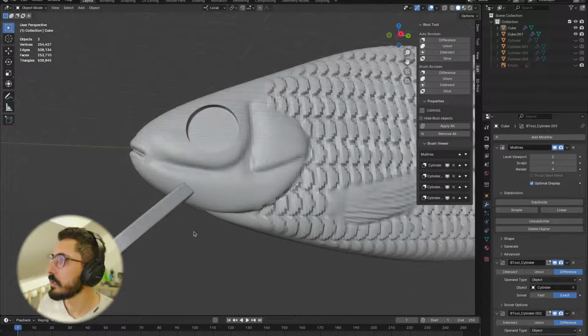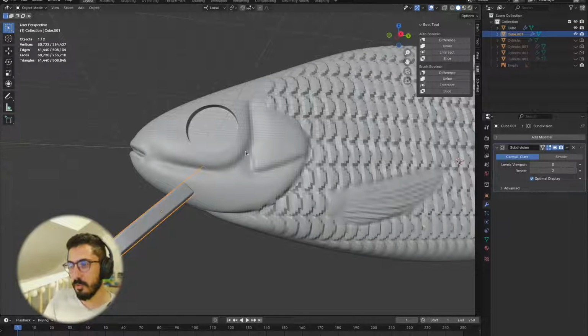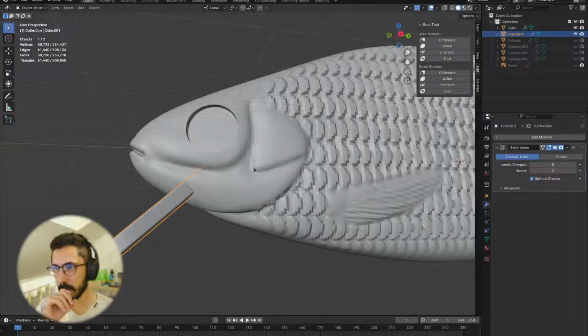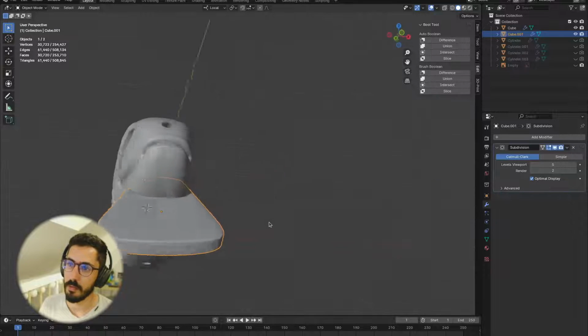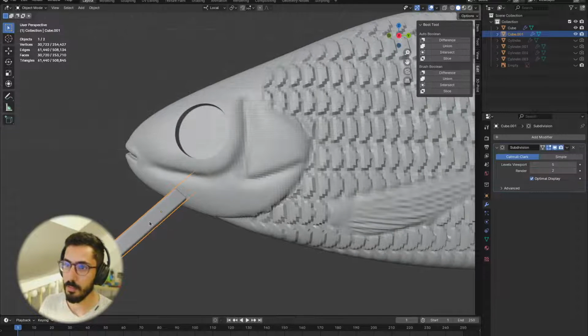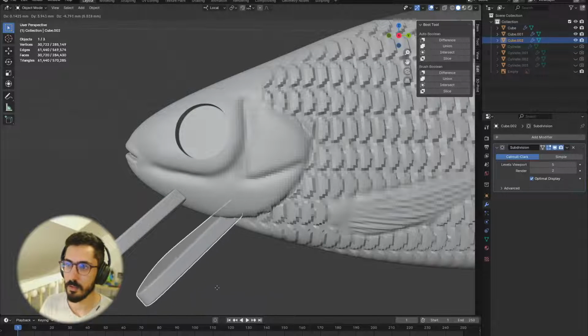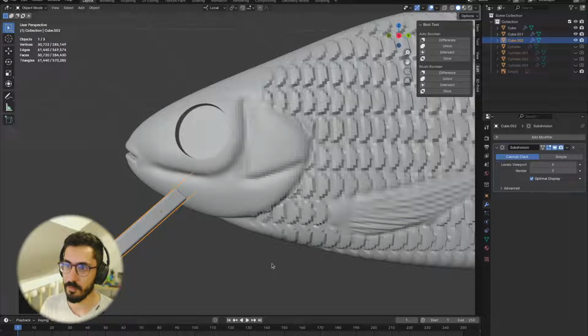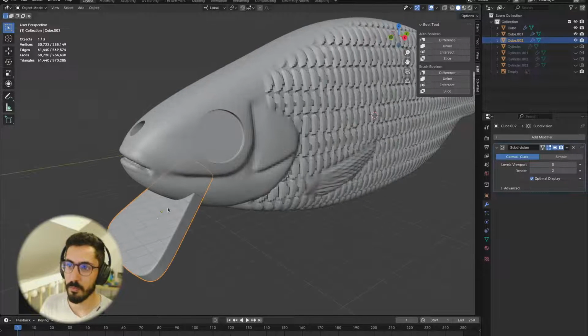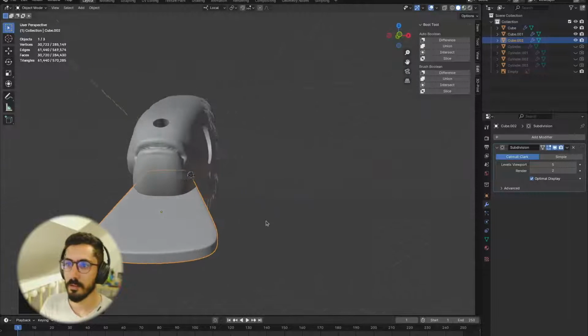And okay, so I can't just cut this from the lure and call it a day, because we need some tolerance or some clearance in order to assemble this later. So I'm gonna duplicate the lip. Shift D. Okay. But I'm not gonna click anywhere. I'm gonna click escape to leave it in place. So now we have two lips in the same place.